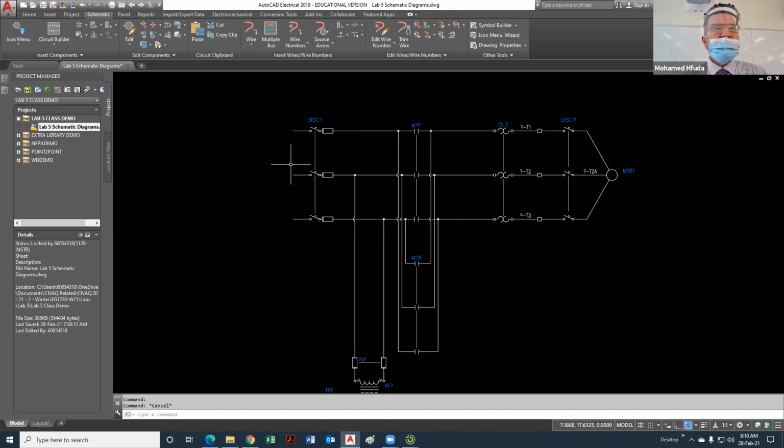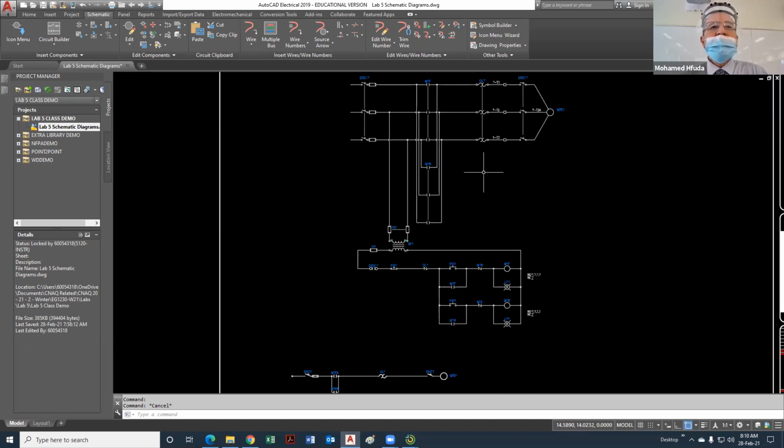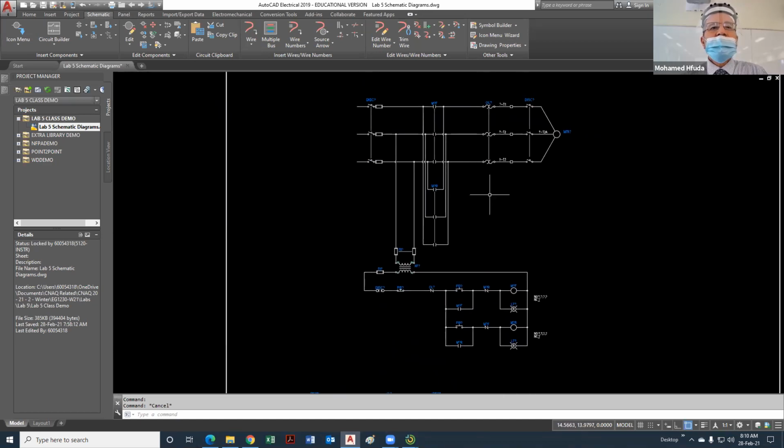The supply is the supply. You don't change it. Now, one thing you want to be absolutely sure of is that you don't want these contacts to be closed at the same time. Why do we need that? What happens if we do? Short circuit. Between those two phases that have been interchanged, it's a short circuit.